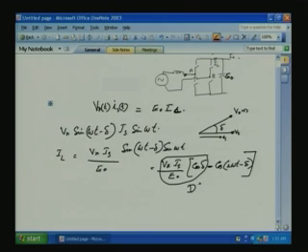This is the DC part, that is equal to the I0, and there is a fluctuating part, that is at 2 times the input frequency. This will go through this capacitor. So, we have to design the capacitor for this 2 times the frequency. There is a second harmonic current flowing through this one.